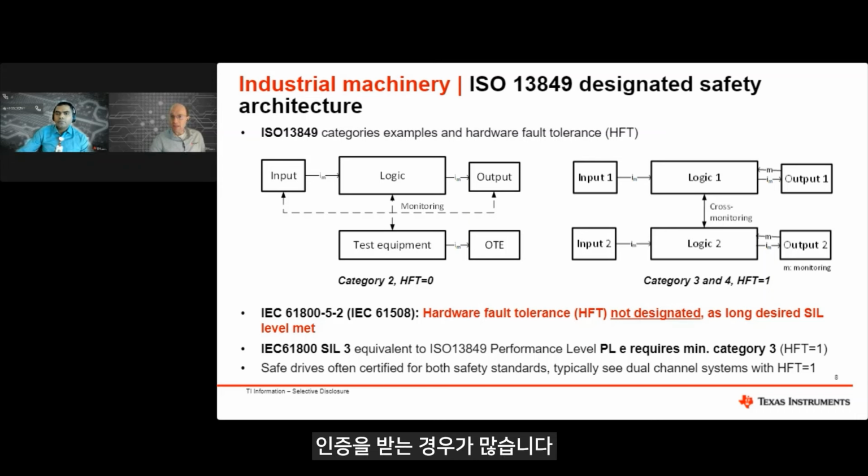The actuation safety is supported by redundant peripherals with the on-chip CLB, the configurable logic block, and other modules that can be used as a smart comparator without causing spurious trips or false alarms in the system. To support safe communication, the microcontroller has built-in hardware features, including memory ECC and parity, and software test libraries for the core. The microcontroller can support multiple safety functions, possibly with different safety integrity levels for each one of them, and they need to coexist on the same microcontroller. So the MCU supports features in the hardware which help keep isolation between the various safety functions. More details on the device safety concept can be found in the individual device's safety manual.